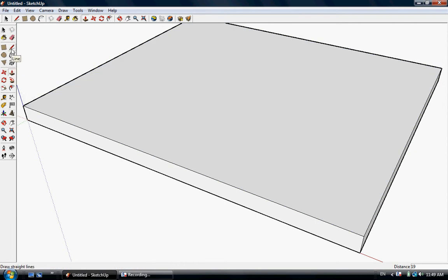What we're going to do is identify our different coloured timbers that we've used. So I'm going to use this tool here, which is called tape measure, and I'm going to left click from the side. I don't want to go from the end or the midpoint, because that can sometimes throw out the measurements. So I'm going to left click and drag in the direction I want to go. Notice how the arrow is green. That's a good thing because we're moving on the green axis. We're developing the width of it now. And I'm going to type in 70 because our boards were 70.